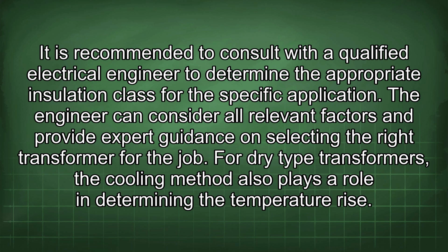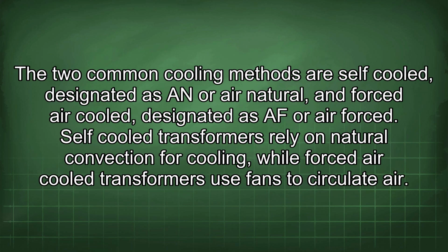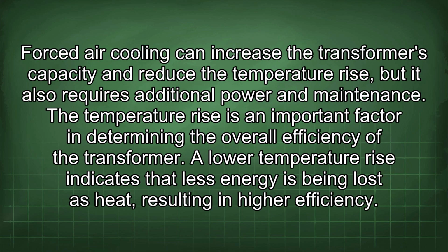For dry-type transformers, the cooling method also plays a role in determining the temperature rise. The two common cooling methods are self-cooled, designated as AN or air natural, and forced air-cooled, designated as AF or air forced. Self-cooled transformers rely on natural convection for cooling, while forced air-cooled transformers use fans to circulate air. Forced air cooling can increase the transformer's capacity and reduce the temperature rise, but it also requires additional power and maintenance. The temperature rise is an important factor in determining the overall efficiency of the transformer.